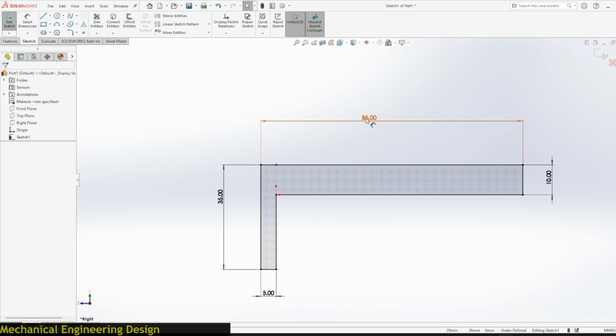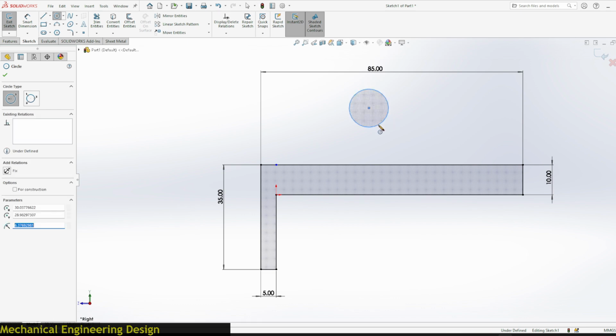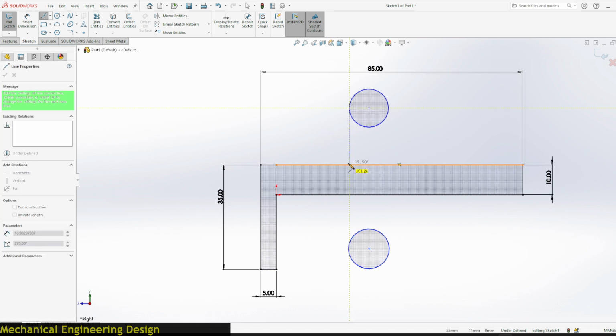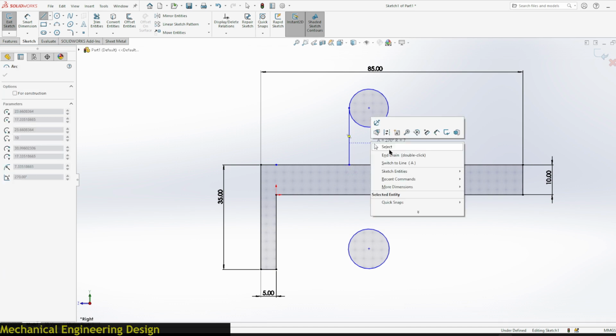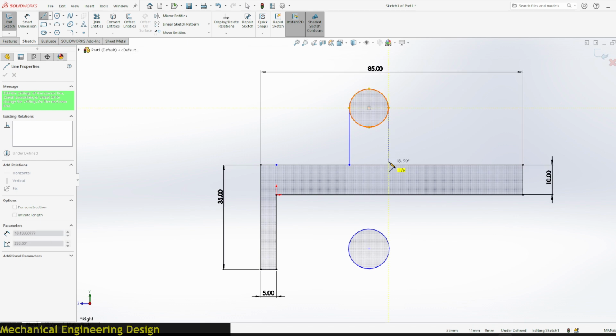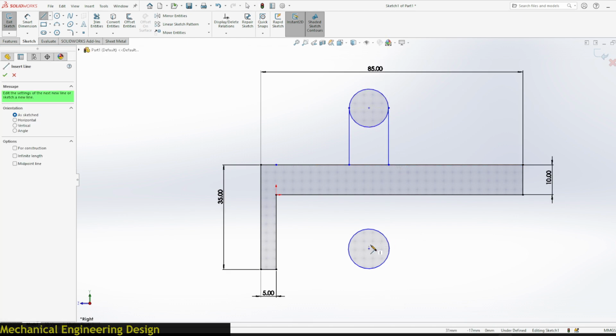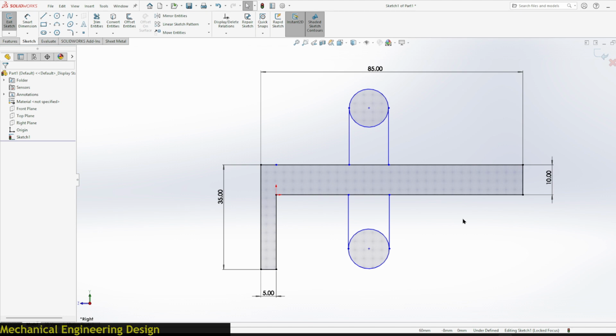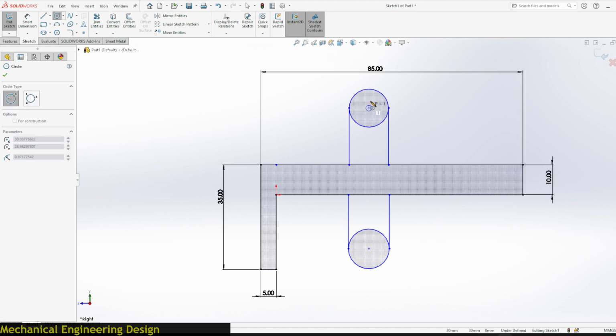Sketch is fully defined. Now we go to the next part, where we pick circle and draw a sketch here, and the next circle downwards here. Using line, we'll drop a line which is perpendicular to this line. Enter. Draw the second line from this quadrant, perpendicular downwards. Repeat the same on the lower circle. Like that. Then we can draw another circle inside and another one inside here.